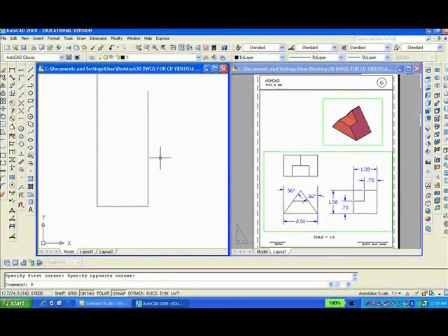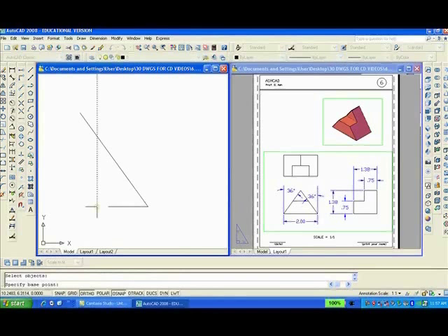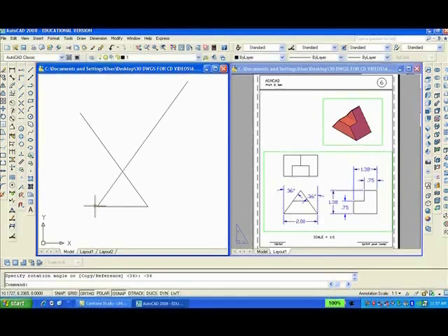I'm going to rotate, RO, enter. I'll rotate the line on the left from its base point counterclockwise, so it's simply 36. Enter. Rotate the line on the left, rather, from its base point minus 36. Enter. F enter for fillet, radius 0, clean up that intersection.